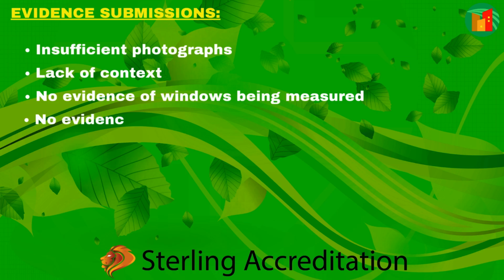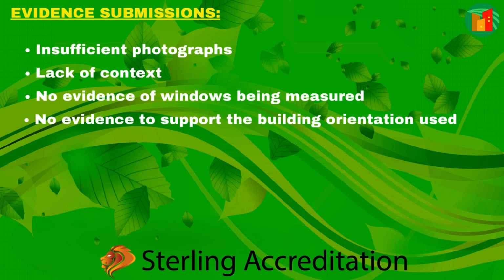No evidence of the building orientation used. Another input factor in the new assessments is that the correct building orientation is used. This should be clearly evidenced and can be easily done by showing the property location on an aerial image alongside the orientation. This has always been a requirement of non-domestic assessments and free software is available that can provide this.